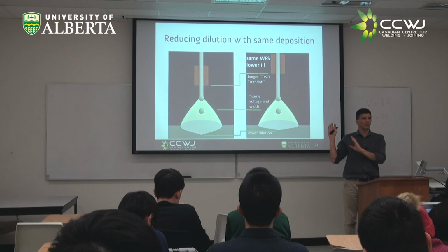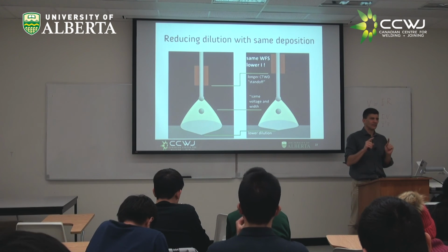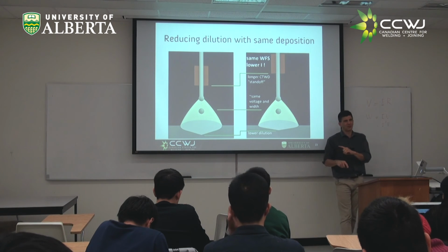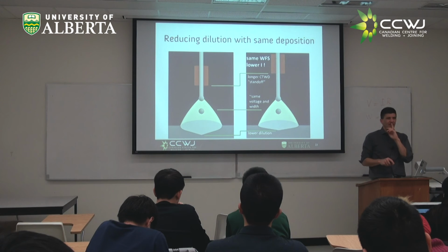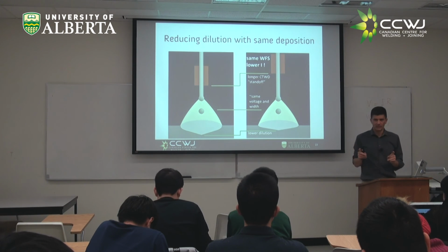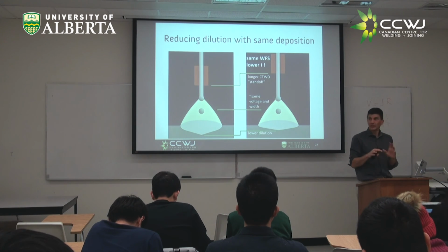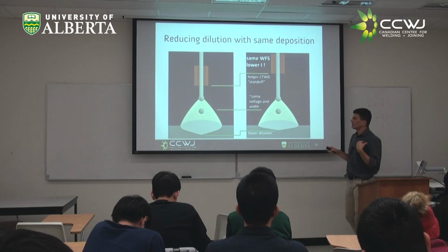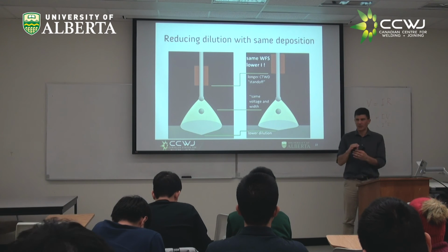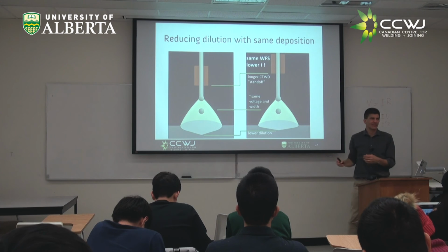This is submerged arc welding, and it's more or less like MIG. They were running on constant voltage. So you can play with the voltage, but you don't touch the current. You touch the wire feed speed. So this is what they did. As you realize, with all you know, you're more or less circling around it. But many people don't even know what you know, so they couldn't even circle around. What they decided to do is something that very often people say don't ever touch. They changed the torch standoff, right? The contact tip to workpiece distance.